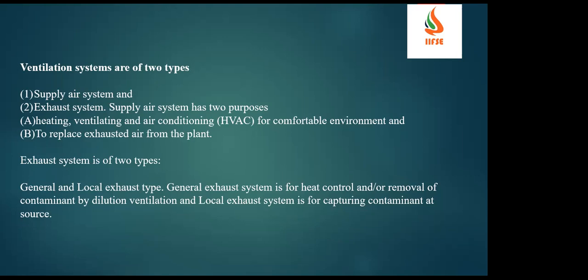Local exhaust system, in the sense it is specifically for a specific location. I can take an example of a welding booth. In a welding area, they produce welding fumes. There I'll install a local exhaust ventilation system, so that whatever fumes are generated from my welding process are captured through this local exhaust system, then put to the collection system. That is for ventilation.